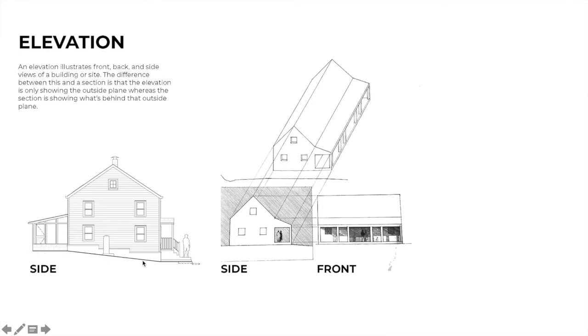There is a cut here similar to the site section we saw before. There's a nice bold line here that represents the slight topographic change that might be on the site. And you can see how the architect has responded to that by making the floor level probably consistent and allowing the basement level to disappear below grade. You can even see this perhaps stepping down to the sidewalk level here on the street edge.